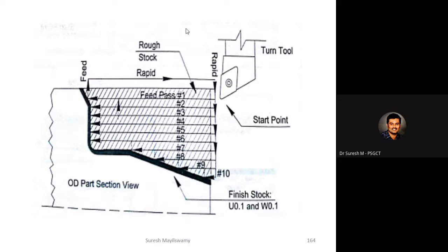So this is the cutting tool. It will first start here, then pass up to this edge. This is the first pass. After that, there is a retract height. What we give in R is the retract height, and then it will move at rapid traverse. Then it will enter down. This is the depth of cut.